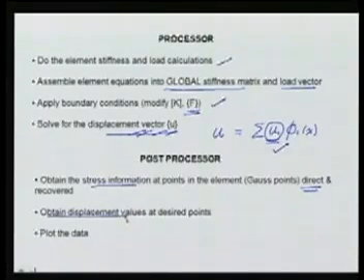So in the next lecture, we are going to look at the remaining pieces of the modules. Remember that the integration, the shape functions, and the element calculations we have already done. How do we fill in the rest of the part? That is making the mesh, then creating the degrees of freedom information, then this global to local enumeration, then applying the boundary conditions, and so on. Solver, okay, we'll talk of those. We'll talk of a simple post-processing scheme to get better, so-called better recovered stress information, and then the program is essentially ready. Thank you.